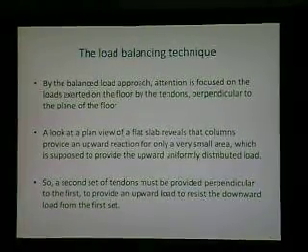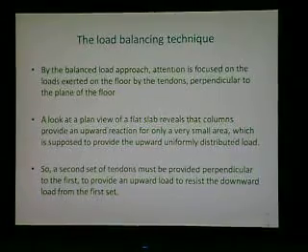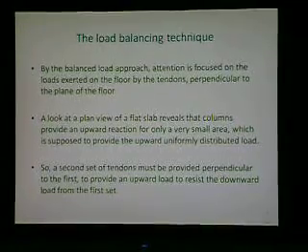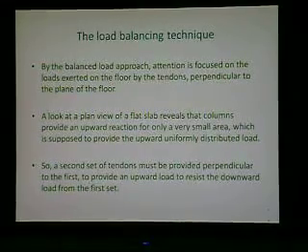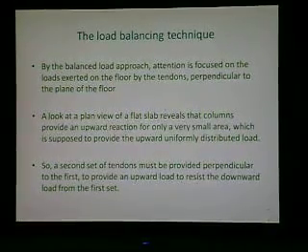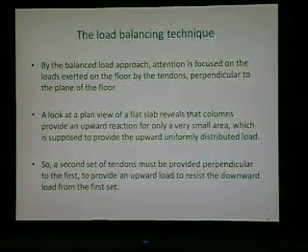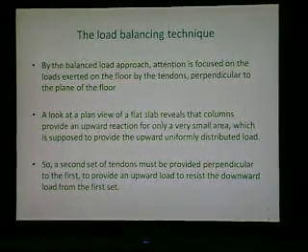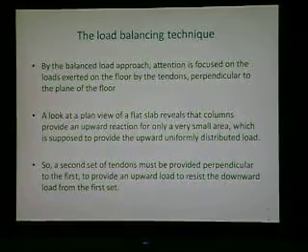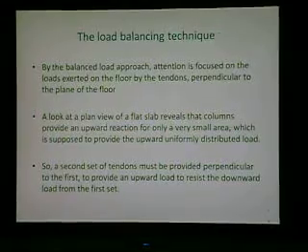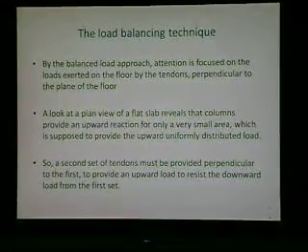The load balancing technique. By the balanced load approach, the attention is focused on the loads exerted on the floor by the tendons perpendicular to the plane of the floor. A look at a plan view of a flat slab reveals that columns provide an upward reaction for only a very small area, which is supposed to provide the upward uniformly distributed load. So a second set of tendons must be provided perpendicular to the first to provide an upward load to resist the downward load from the first set.